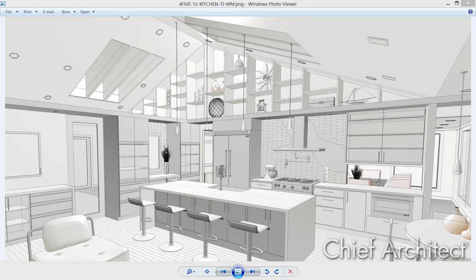The final ceiling style for our kitchen is an open vault with some shelving above. This vault is actually more than just removing the ceiling out. If I did that underneath the roof, the ceiling would follow the roof pitch. And depending on what size of rafter I may have used, I may not be able to get proper insulation.